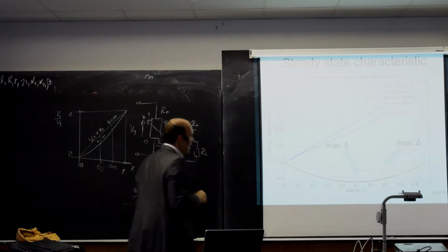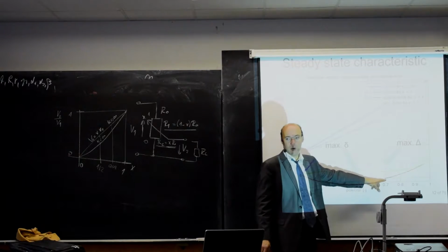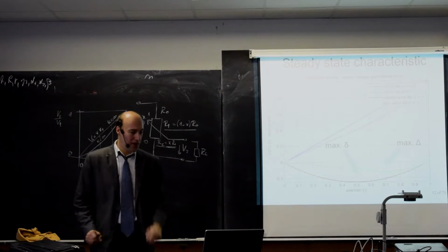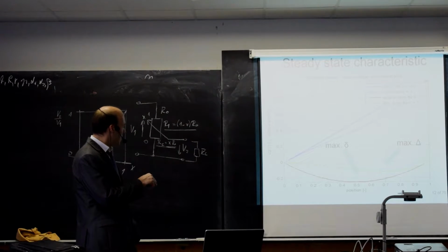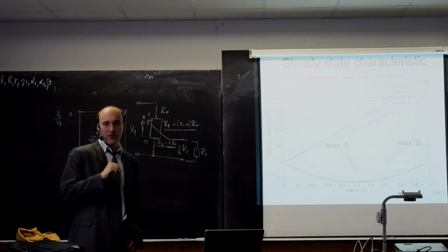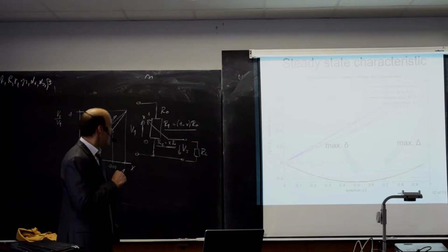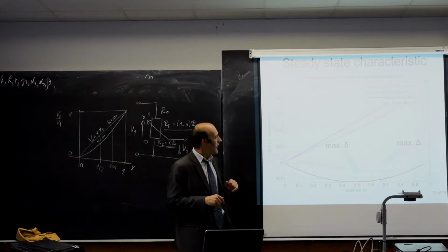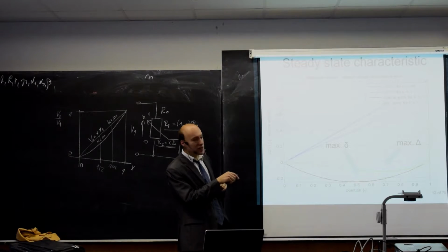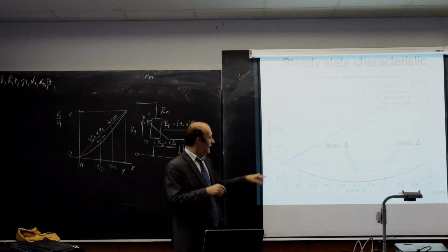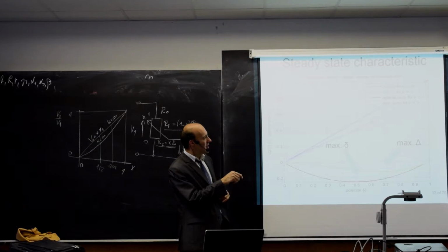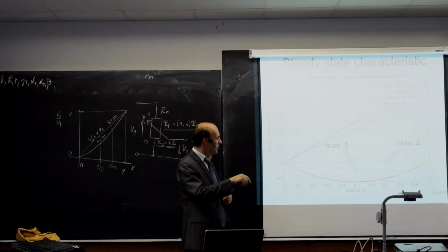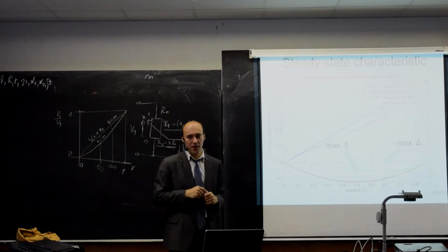The maximum absolute error is somewhere around 0.7 of the full scale. But there are also two other interesting points. At position 0, you see that relative and absolute error is 0. So here we are measuring accurately because we measure 0 voltage. But the same happens also at full scale over there. So at this point and at this point you always measure with 0 relative and absolute error. But in the middle you have the highest relative error.